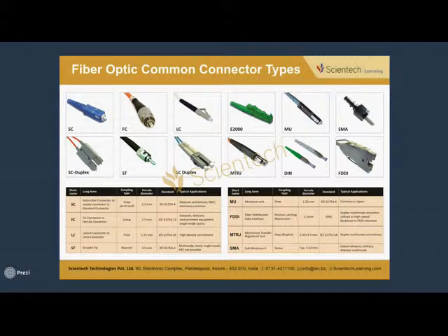The LC connector is a relatively new standard developed by Lucent Technologies. The LC is classified as a small form factor connector. The term form factor refers to the physical attributes of a connector. The LC connector is approximately half the diameter of an SC or an ST connector.